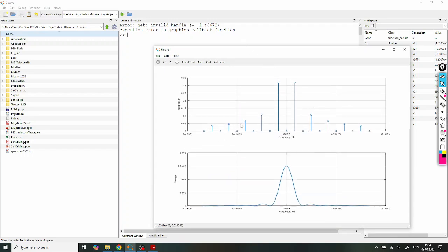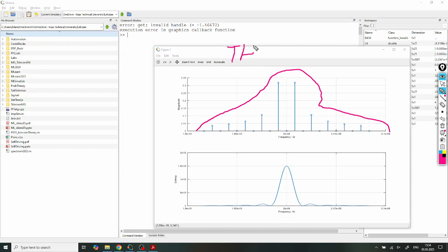You have two pictures. One is the spectrum of magnitude for a periodical signal, and one is for a random sequence. Now you need to realize that from the perspective of the spectrum requirements, most often this one is the good indicator, because this is considered to be the worst case scenario. So if your system and your channel and your cable or whatever else can handle this spectrum, it's easily going to handle any other combination spectrums.